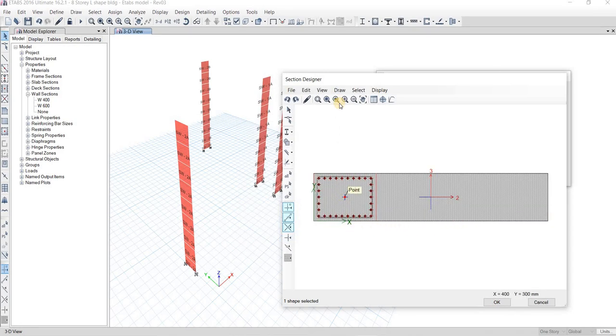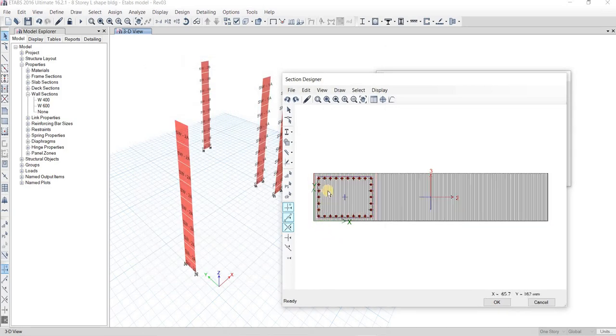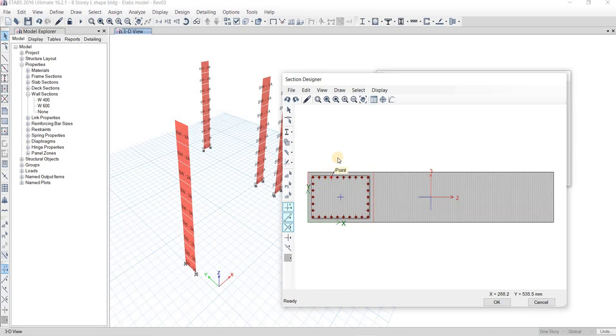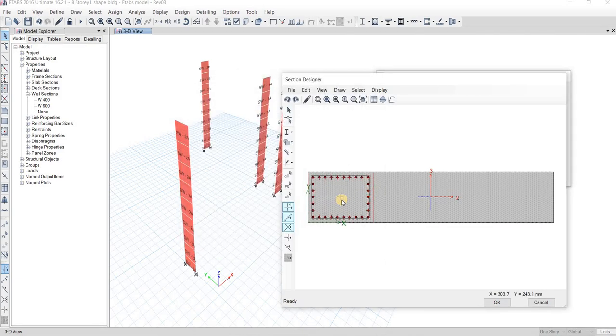layout. So total, I have a number of, so this is 8 plus 8, 16. So 20. Then I have here 5. I have 30, 25 mm longitudinal bars. Then I will just copy or mirror that one.